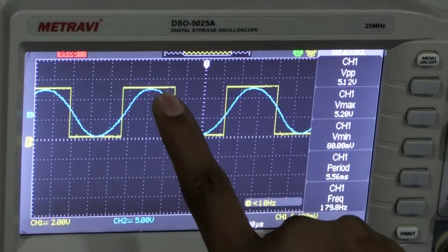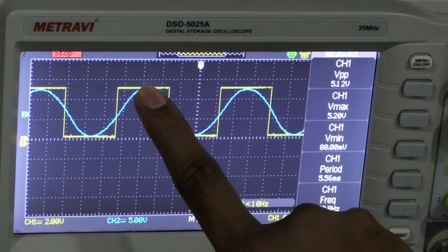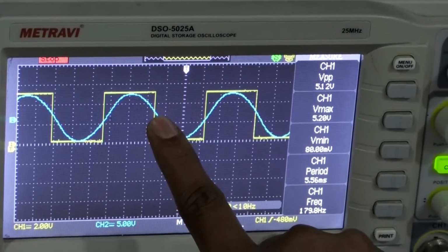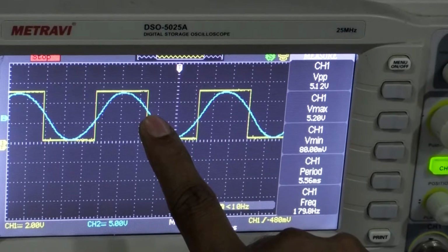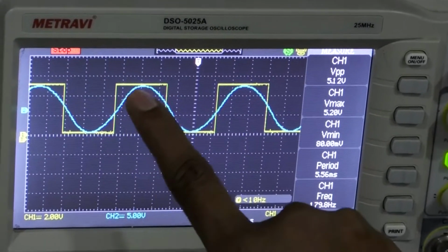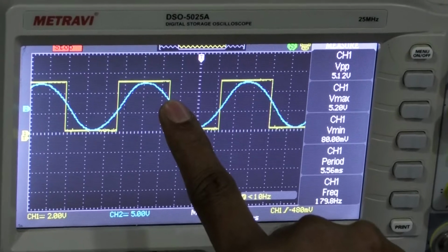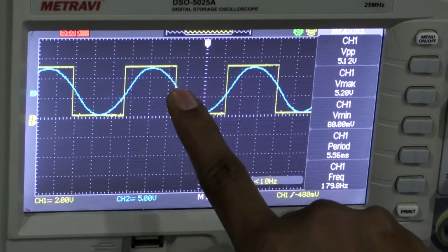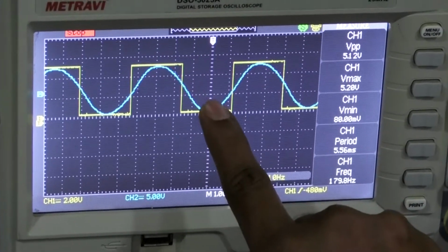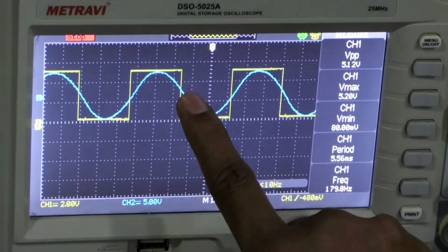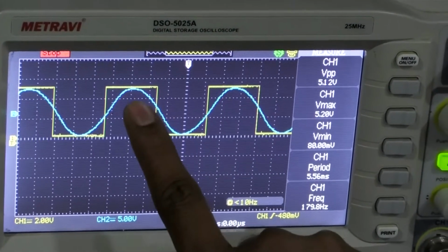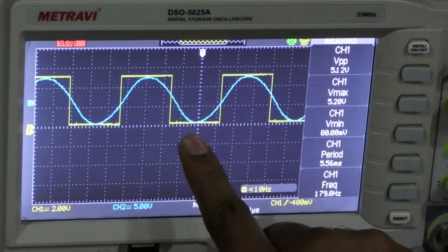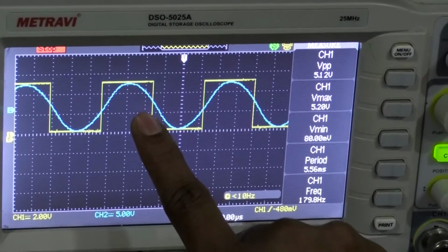From here to here, the signal is increased. I already told you in terms of the staircase signal: if the step is increased, a 1 is transmitted. From here to here, the signal is decreased, which means the step signal is less than the previous value. In that case, we transmit only 0 values. That's why the ones and zeros combination of the delta modulation is produced. So this is about the delta modulated output.